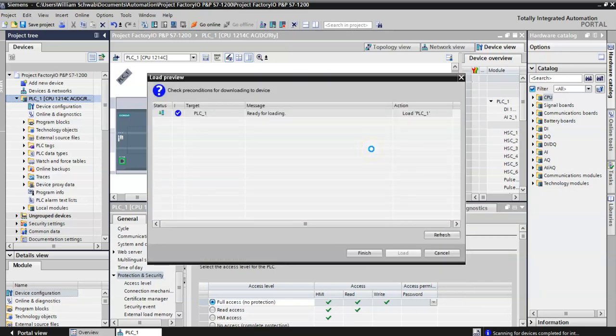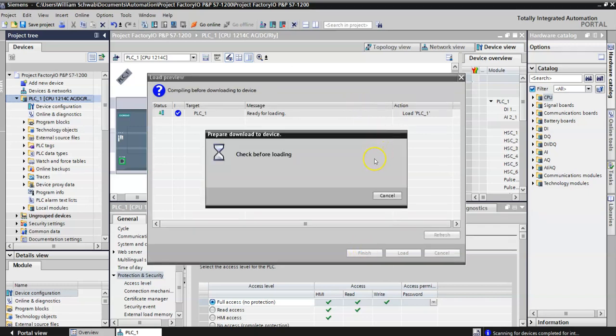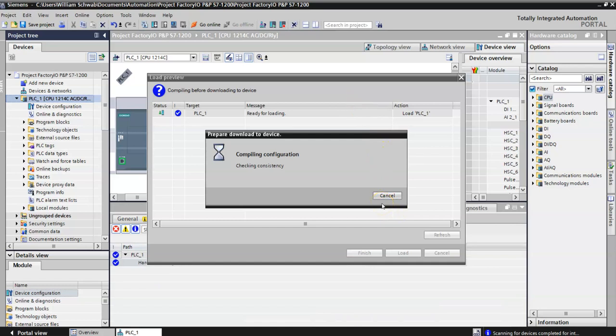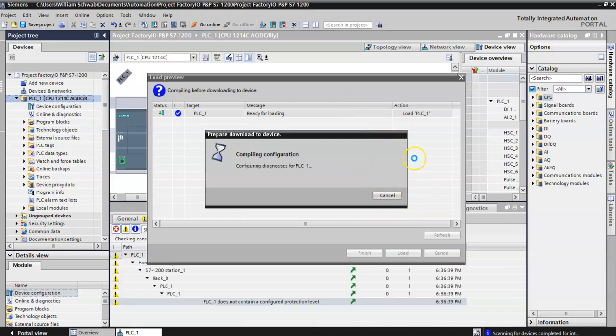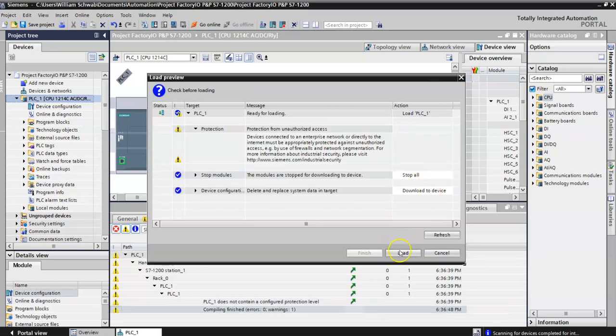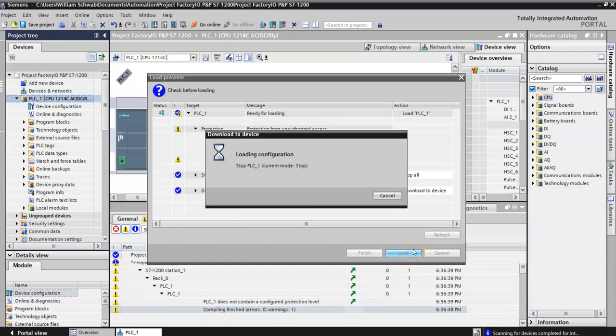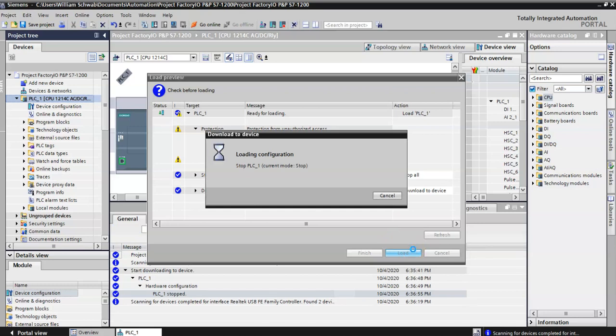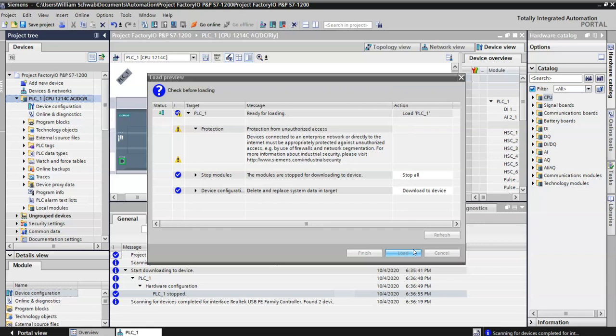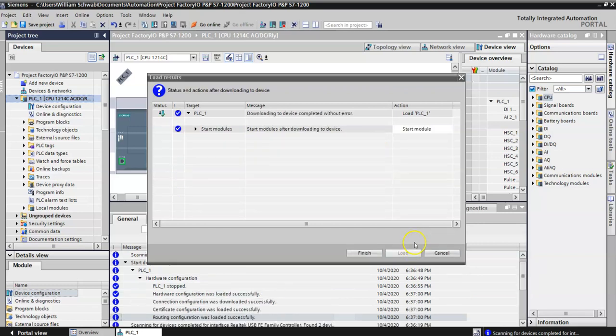If you like this type of programming, it's not so helpful with this program, but if you get into more complicated programs, it's really helpful. And I think we'll do some little videos on more complicated Factory I/O, along with doing them with this type of the structured control language or structured text. And I think the best bet is to combine it. The really high level stuff is better off in the structured text. The lower level stuff can be in the lower level. You can combine ladder logic with structured text. You can combine function block diagrams with it.